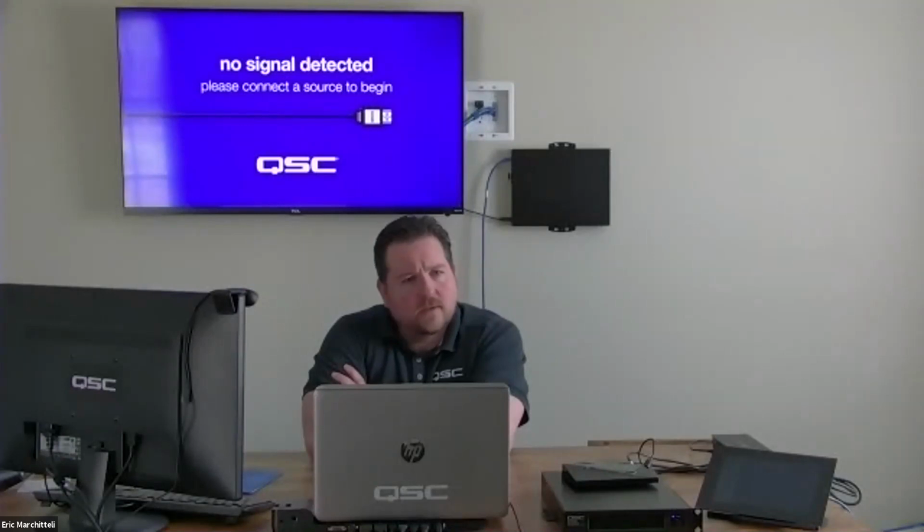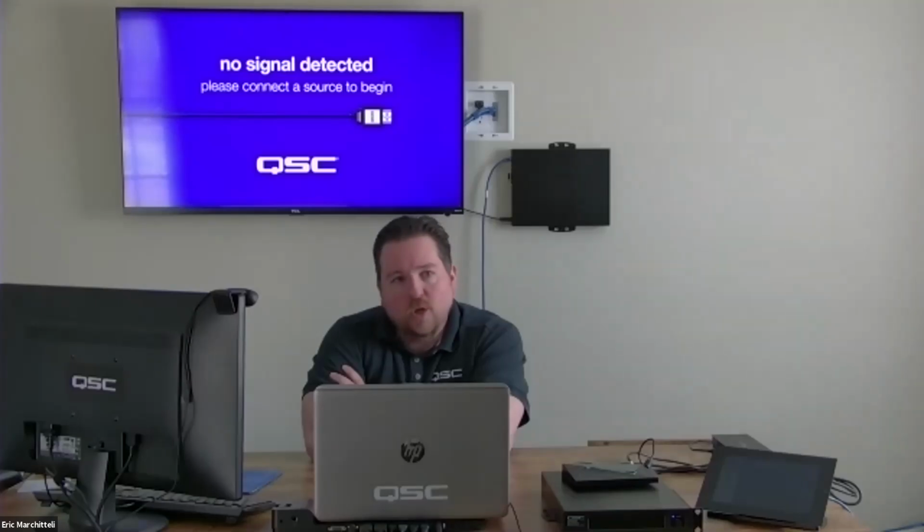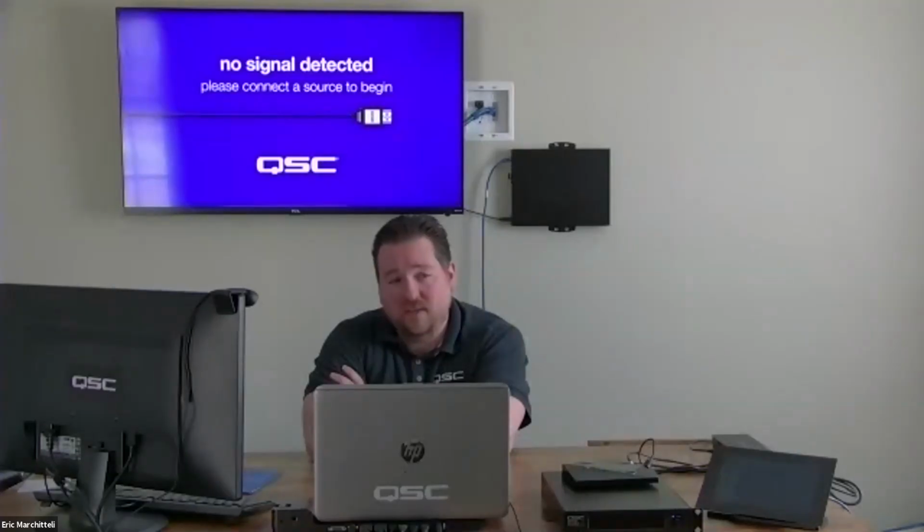Does the NV pass through any bitstream surround audio on HDMI? Does it do any pass through of that bitstream? So the NV, can you guys hear me? Yes, we can. Cool. So the NV will only accept PCM audio. So if you have a device that's able to decode, like a Blu-ray player that can decode DTS or anything like that and pass it out as 7 or 8 separate channels of PCM audio, the NV can accept those, up to 8 channels that way. But it won't do any decoding such as DTS or Dolby. It can't decode that type of audio. Got it.